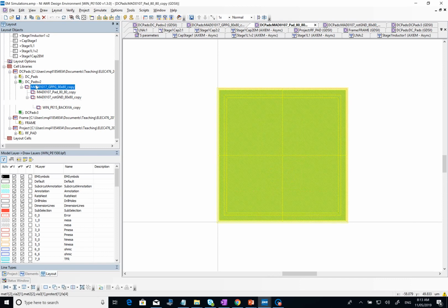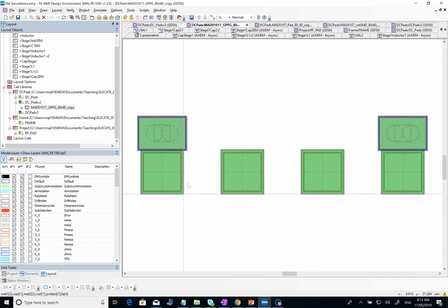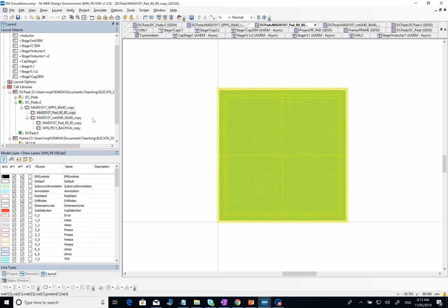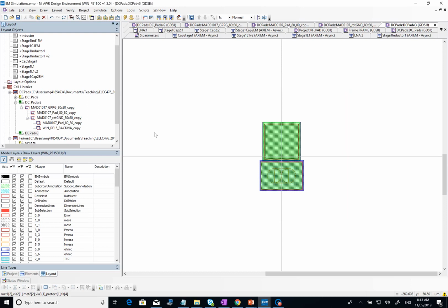Oh, we have to check how far they are. You don't have to do this, it's just me doing for you. I need to check the length between them. I think it's 150, yes. So I put the first one at 0 0, so I have to put the second one, just this copy. So I'll put it x150 y0. Okay, that's fine, because the 0 0 point is here.